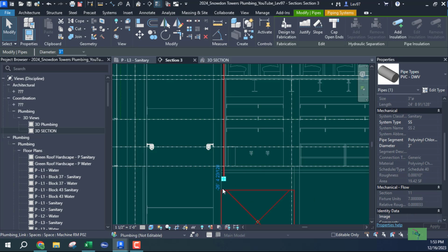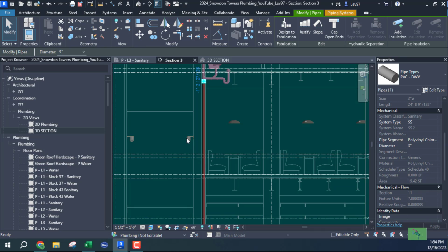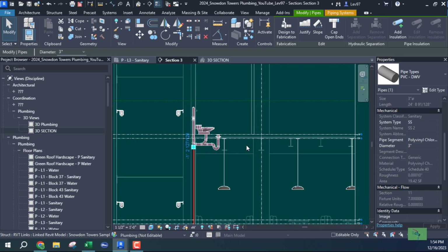The nightmare is when you click on it and the fixture unit says 0, and you know you got a whole system that you know is at least, let's say it's 67 drainage fixture units, and it's 117 water supply fixture units, and you're getting 0.